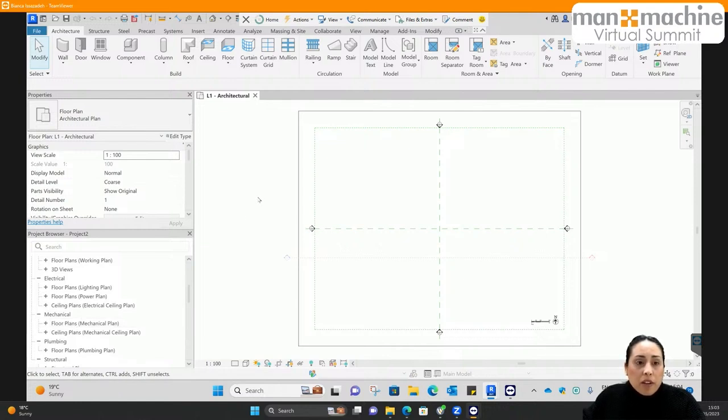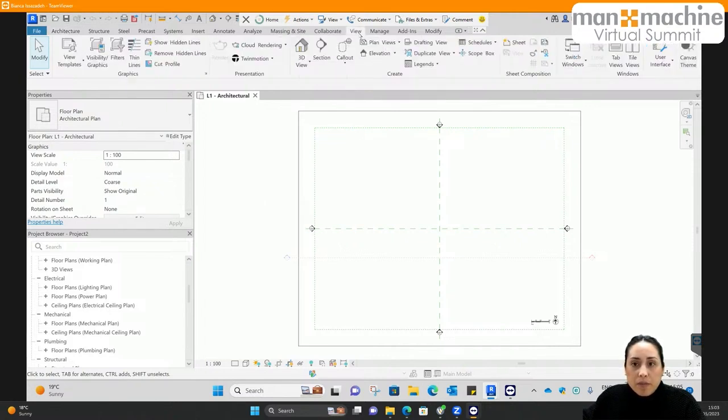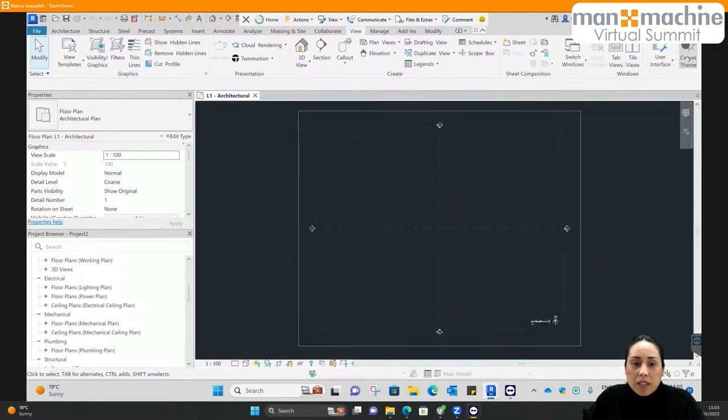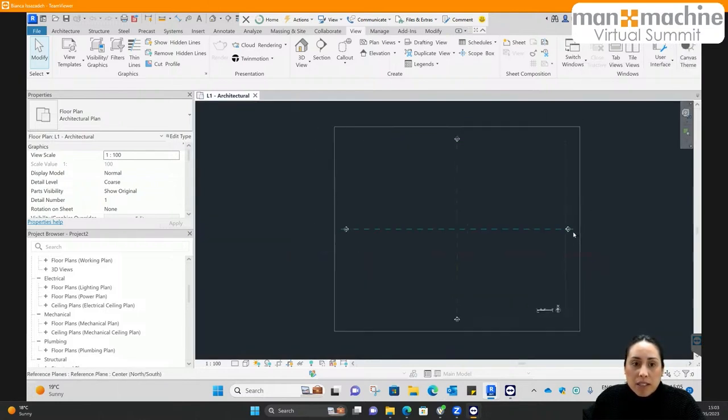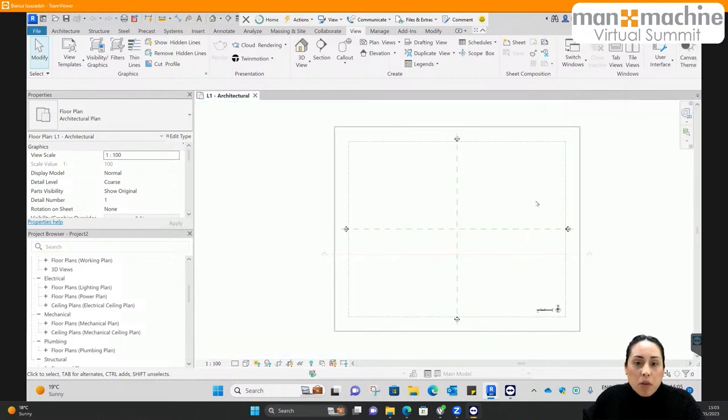From there, if you'd like to use the dark theme, as I mentioned, we'll begin in the View tab. And on the very right side, I have the Canvas theme. So if I select Canvas theme now, that's going to go into the dark mode in my model space, paper space. Now, if you're like me, you prefer the traditional view, I'm just going to change that back to the light theme, but I will show you how to change the overall look.